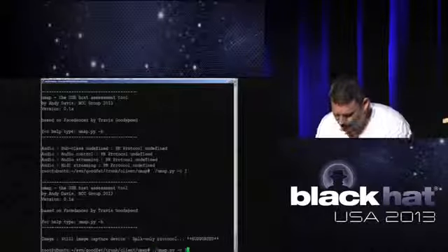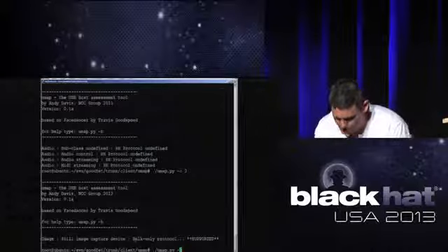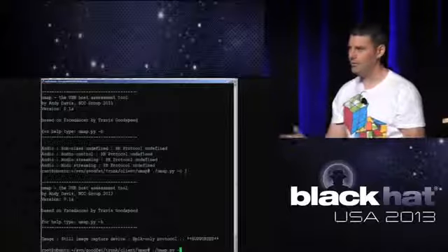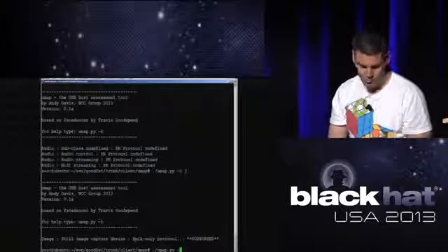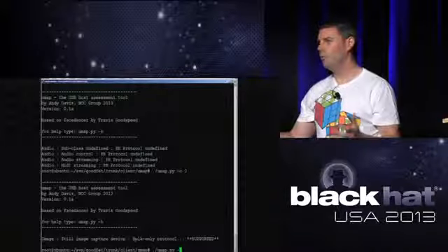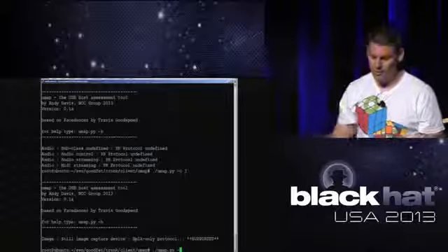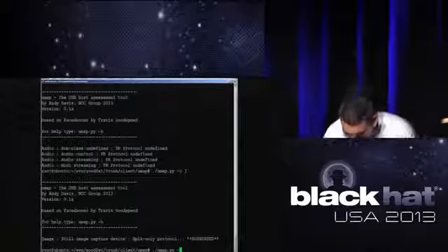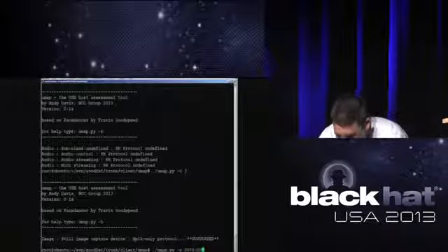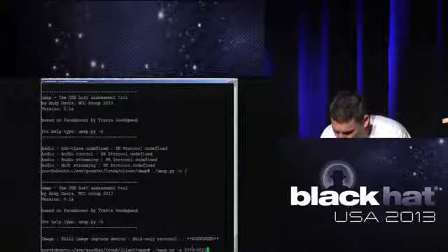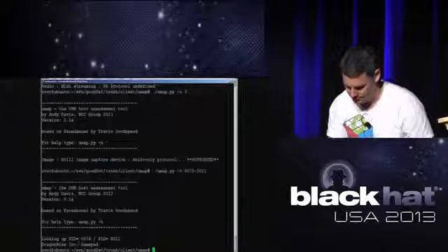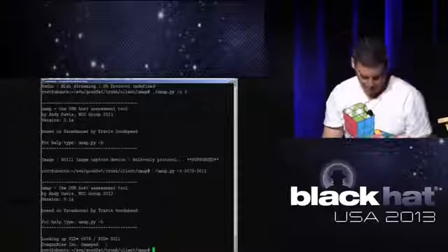Another thing you can do with UMAP is, if you've seen the VID and PID, the vendor ID and product ID numbers, in the captured traffic, and you want to decode those. I mentioned that there's a publicly available list of all the registered VIDs and PIDs. The tool downloads that and maintains a local copy, and you can do a lookup. So that's VID and PID. The vendor is Dragon Rise Inc., and the product ID is for a gamepad.